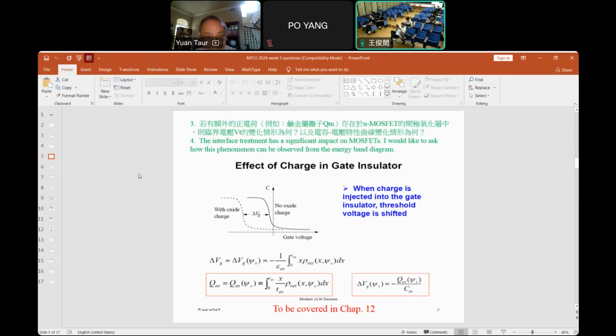Technology process usually is very clean. So we don't worry that much. We worry more about some of the radiation damage and other things, which can cause some additional trap states. During process, you could have UV or whatever, and some of these fixed charge or interface states.